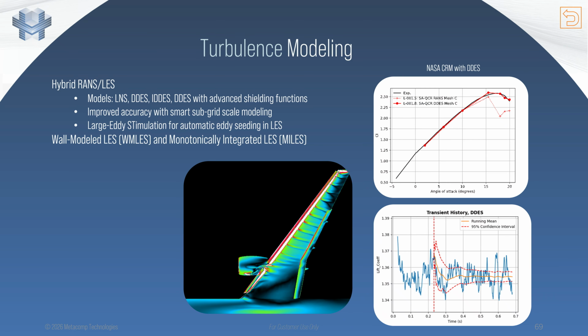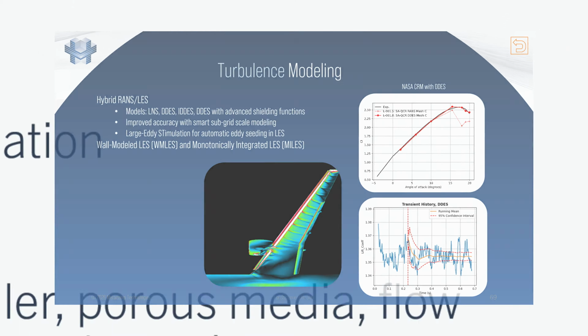Higher fidelity predictions are achievable through the use of large eddy simulation, which can be critical for real-world applications involving strongly non-equilibrium flow, massively separated wake flows, and flow over high-lift devices operating near stall. CFD++ has several approaches to make LES practical and affordable. These methods include wall-modeled LES and hybrid RANS/LES, such as LNS, and various flavors of DDES, including DDES with advanced shielding functions.